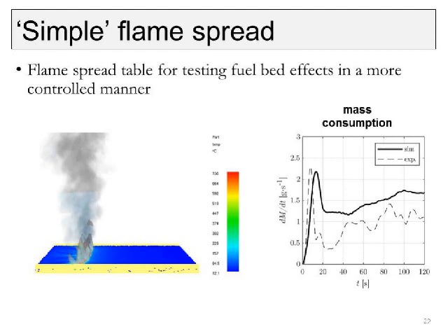And you can see an example here on the right. We have some overall maybe decent consistency, but we do have a tendency to overpredict for these particular conditions, this particular fuel bed. We're overpredicting the mass loss rate, so the energy release. So we might have a bit of an issue here, but this kind of global output variable doesn't do much more for us than tell us that we have an issue. We need to figure out what's going on. So we need to dive a little bit deeper, and that's where the ability to do some of these detailed diagnostic measurements comes in handy.